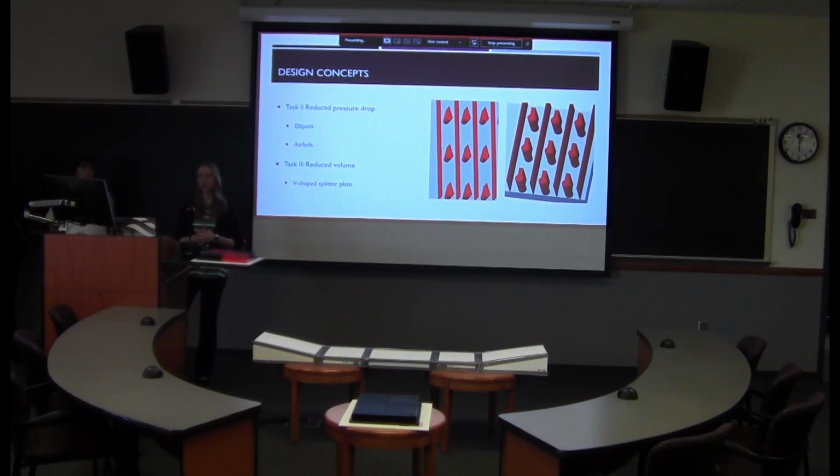For the second task, we focused on pin-fin splitter plate designs. And we did a few variations on those. You'll see on the right, each one has a little pin and then like a plate attached to the back. So we played around with varying the width of that plate as well as the length of that plate to see if we could match that heat transfer in the original design.